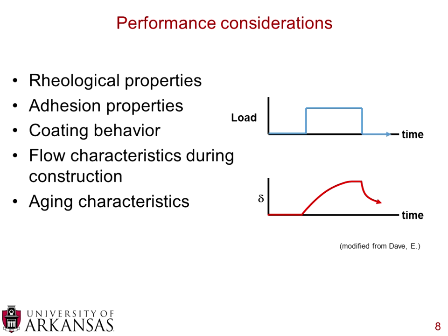What's critical, though, is that you have good performance. Some of the performance characteristics look at the rheological properties. This is the viscosity using the Brookfield rotational viscometer. It's the stiffness characteristics using the G-star sine delta measurements from the SuperPave DSR. BBR testing, that's creep testing for low temperature properties. Those all fall under the umbrella of rheological properties. Also, if you're not using the SuperPave system, you can look at absolute or kinematic viscosity, and you can look at penetration. All these different tests quantify the rheological characteristics of your material.